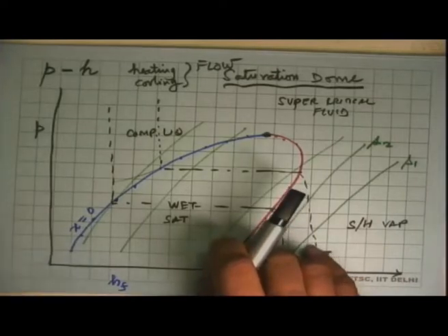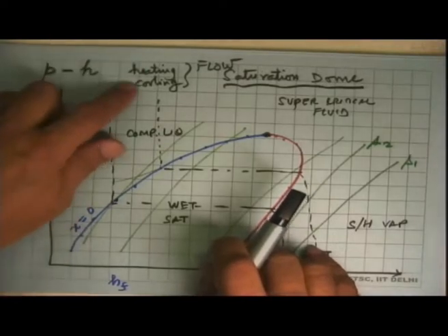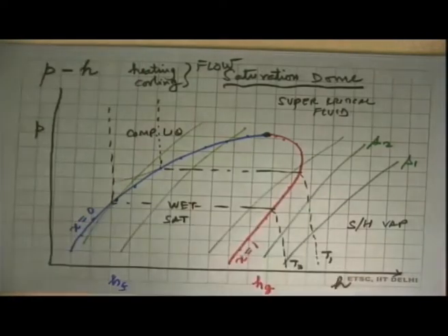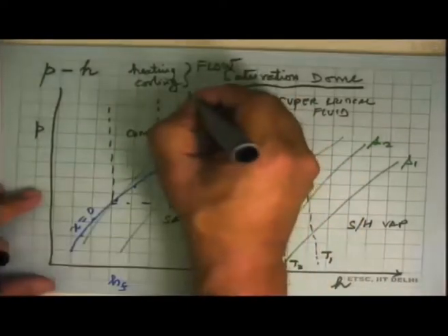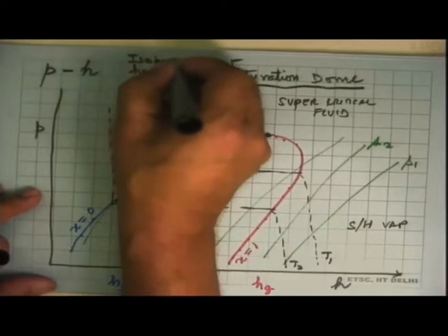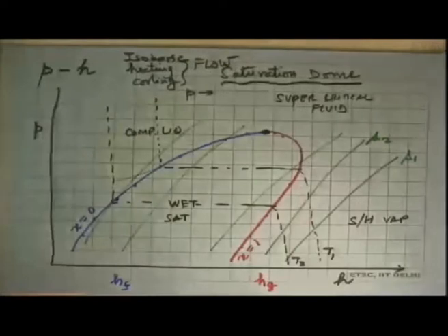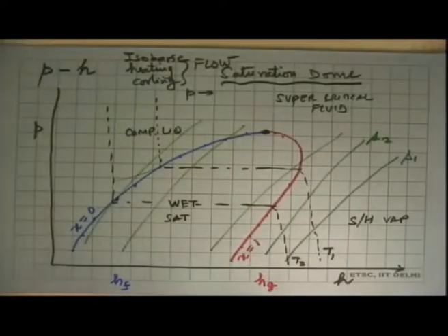In the first cut analysis in thermodynamics, we assume that flow processes involving heating and cooling and no work transfer are constant pressure processes, or isobaric. That's an important assumption we'll make in this course: wherever we look at a flow system and we look at either condensation or heating or cooling, we say that it is isobaric, which is an approximation to the extent that we are neglecting pressure drop in the pipe.